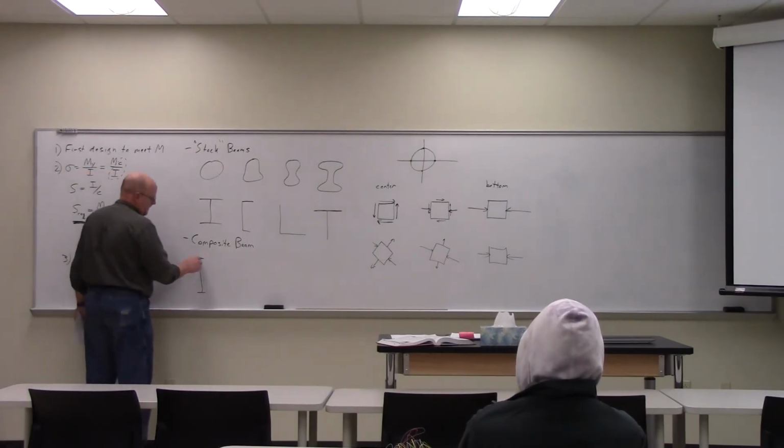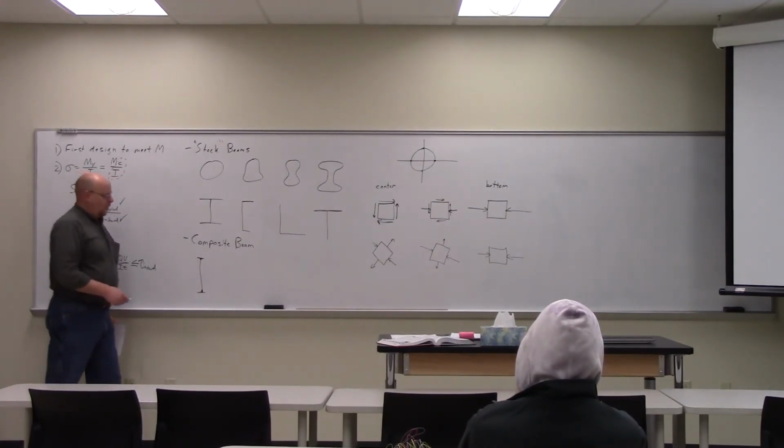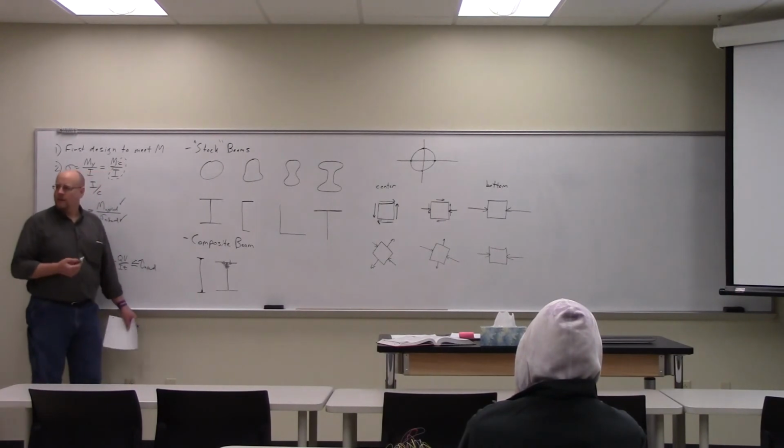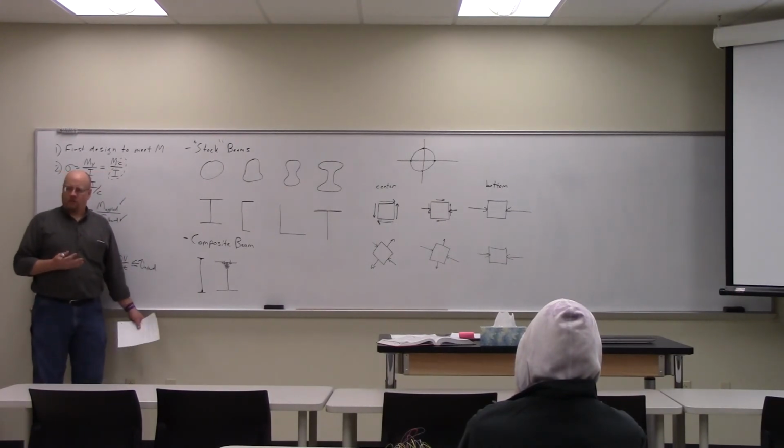All right. So you weld it in here. You weld it at each of the joints. Or you could make something that's bolted on. You could use a short L bracket on each side, bolt through there to a central beam, do the same thing at the bottom. There's different ways of doing it.